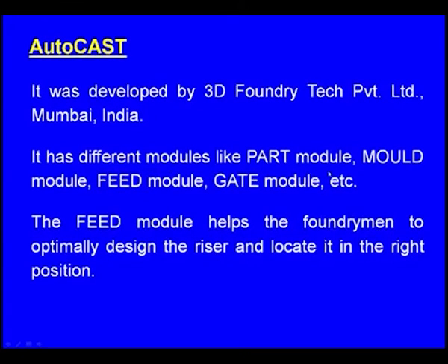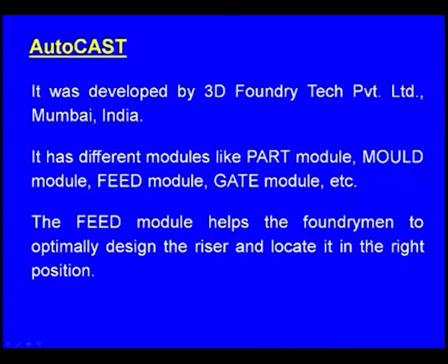One is the part module, second one is the mold module, next one is the feed module and the gate module, and so on. Now, the feed module helps the foundry man to optimally design the riser and to optimally locate it in the right position. So, this software we can use, and this feed module will help us not only to design the riser, but also to locate the riser in the right position.